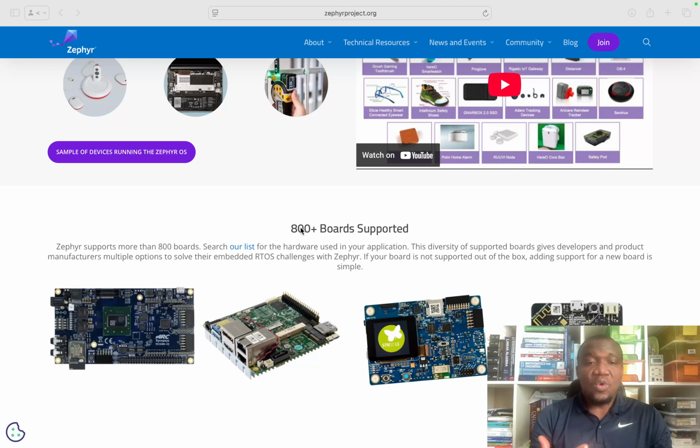If I want to go so low to bare metal, it's basically just defining register addresses and then using bit manipulations to manipulate them. But the beautiful thing comes when I want to switch, or I want to port the firmware from one MCU provider to the other, then I literally do not have to change a lot of things. And that's the beauty about the Zephyr project.